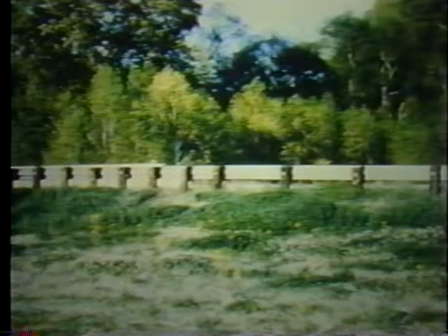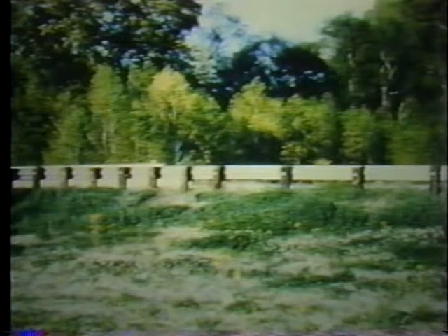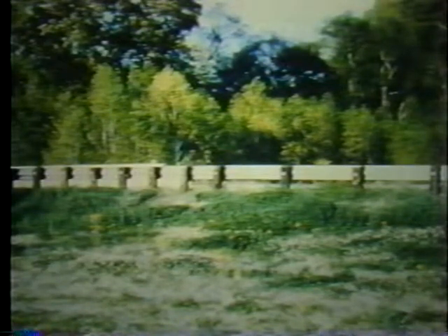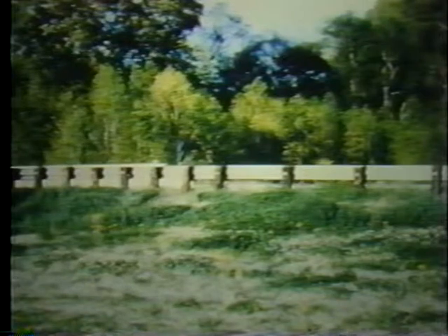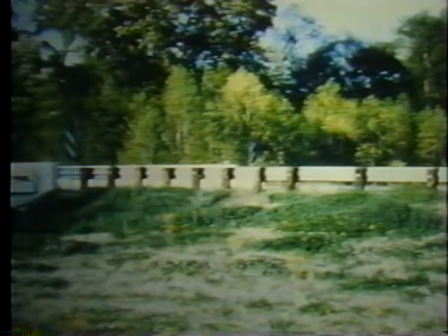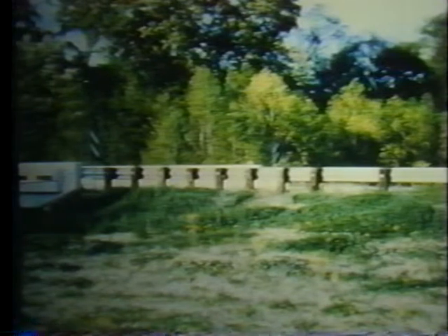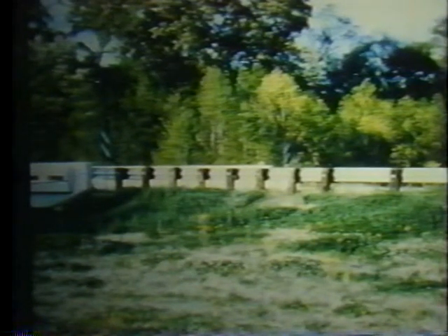Here is an example of reduced post spacing, the most popular method of stiffening metal rails. You can see that the last 25 feet of barrier is supported on blocked out posts on 3-foot, 1.5-inch spacing, or half the normal 6-foot, 3-inch post spacing. In addition, the last 4 posts have 19-inch spacing, so the W-beam becomes progressively stiffer as it approaches the rigid